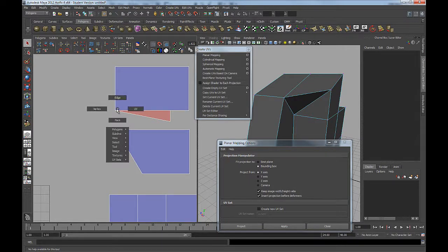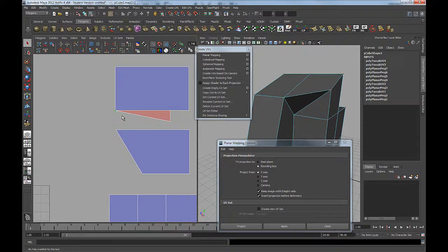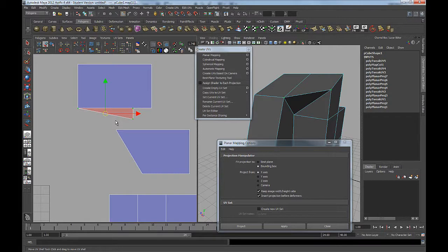So what I'm going to do is right click, select UV, drag a box around that, and come up here to this little cut tool. It says separate UVs on the selected edges. You can also use this one, separate selected UV into one for each connected edge. So I'm going to click that. If I grab my move UV shell tool and select this, now this definitely should not be occurring. There's definitely a problem here. This triangle should separate. Note that with this tool selected, none of these points are highlighted, so technically this should come off as a separate piece. So I'm getting some form of glitch here.